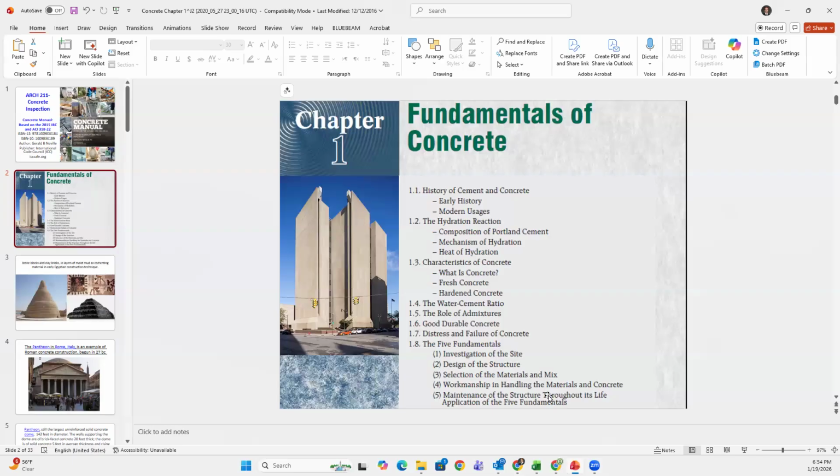To make forms, wood forms, to build a shape like this, you may have to industrialize it. You may have to do precast concrete. One night we'll talk about precast concrete, because you don't have time to form every piece of concrete in this building, but you can make every piece in the shop and put it in the back of an 18-wheeler and bring it piece by piece to the job site and connect them together.